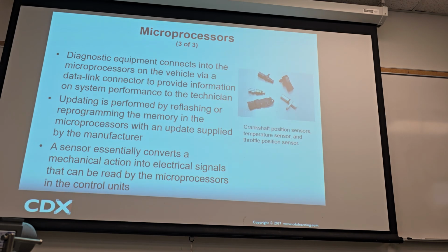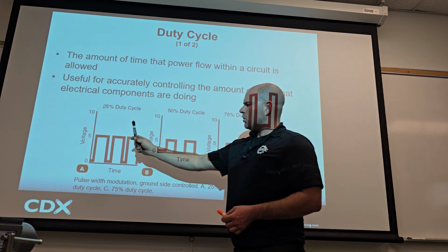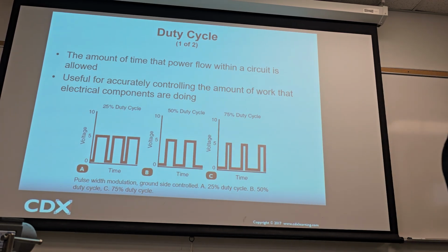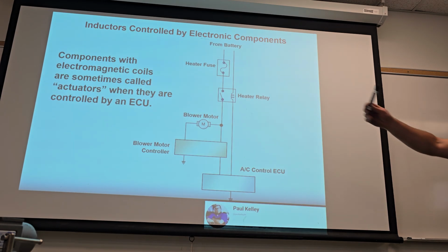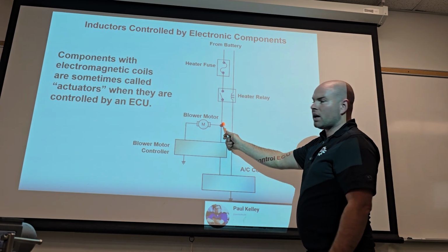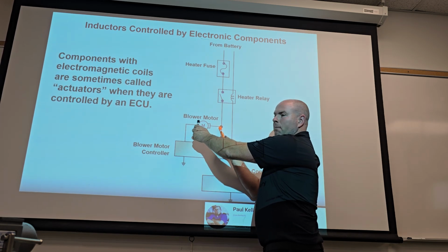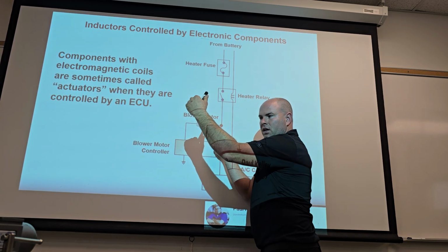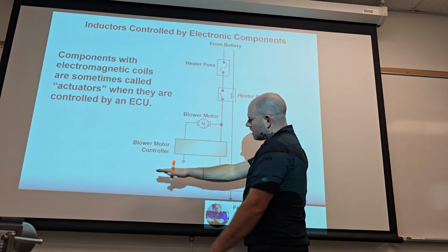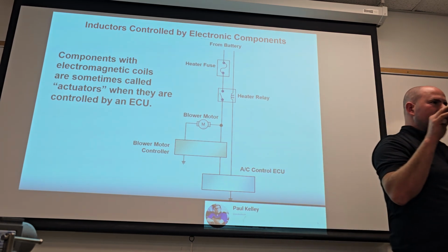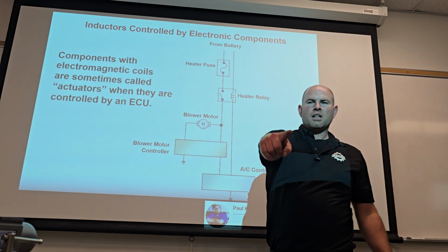So if we look back here, if you want the whole story, you go with the oscilloscope. And how you would do that is really not that different from a meter. You probe your positive up here, because remember, this one should be positive. This one should get what? The ground, exactly. But how much ground? Not ground all the time. It should be ground, not ground, not ground, right? So if you probe it here with the oscilloscope instead of the meter, it'd give you that image right there. It's not that hard. You just have to do a couple quick settings. Okay, so with that, if you don't have any questions, let's do the stop on that bad.